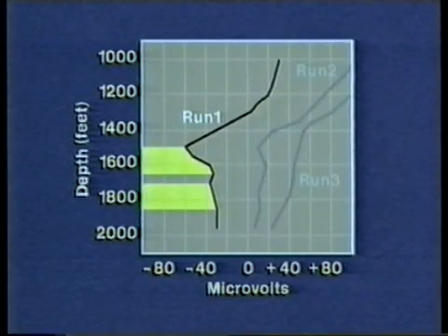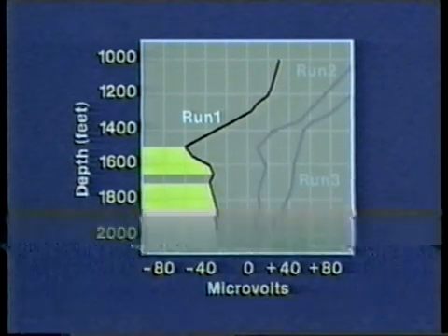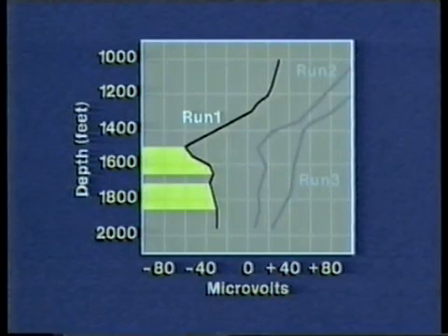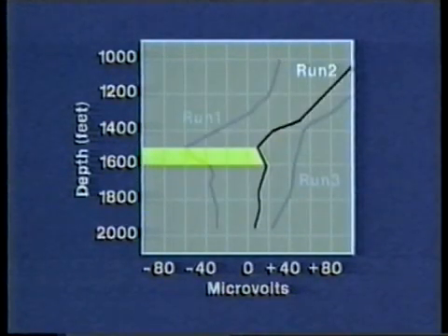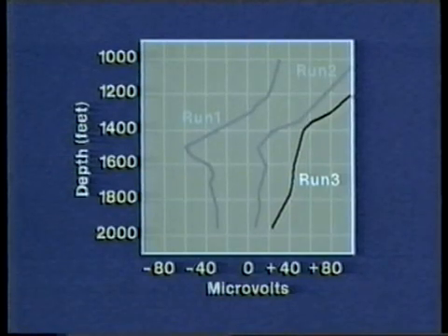Run 1 indicates that the interval from 1,495 to 1,650 feet, 456 to 503 meters, and from 1,700 to 1,850 feet, 518 to 564 meters, were anodes, and hence corroding. Subsequently, cathodic protection was provided by putting a 5-amp current to the wellhead. Run 2, the second casing potential survey, shows that one area still remained anodic. At 8 amps, Run 3 shows that the whole casing string is now a cathode, and electrochemical corrosion is eliminated.